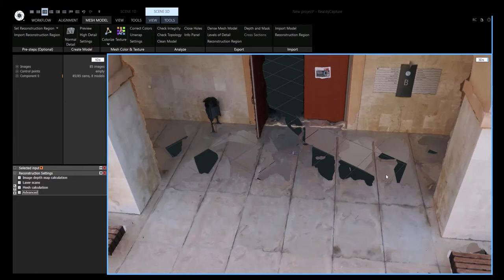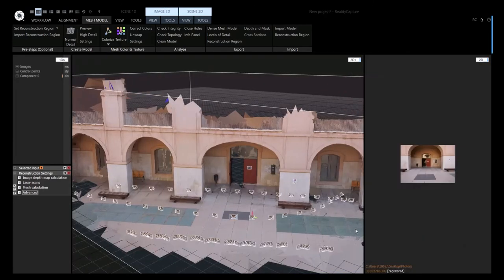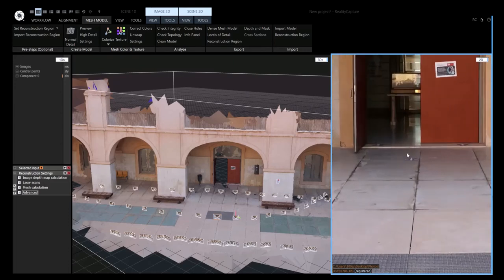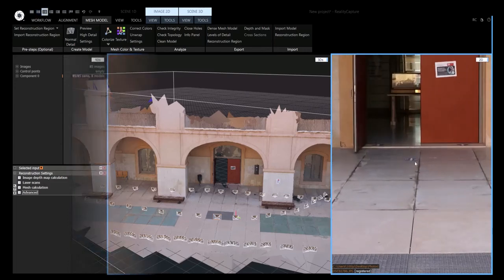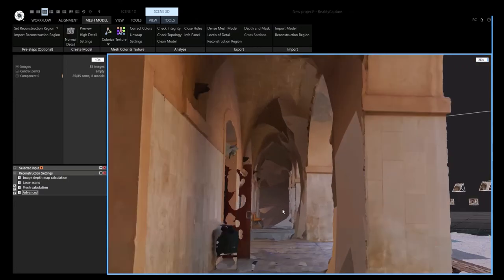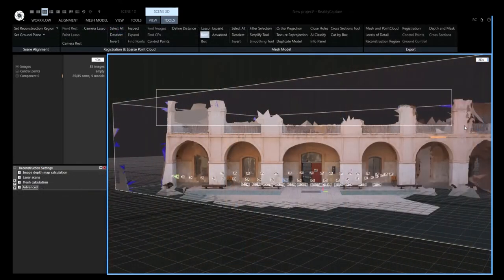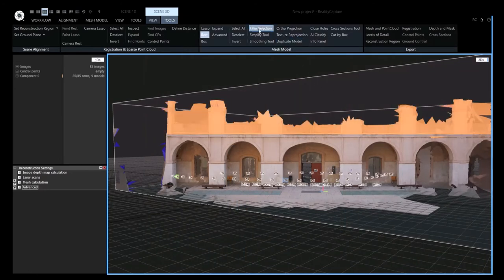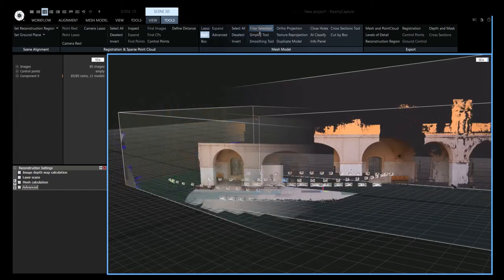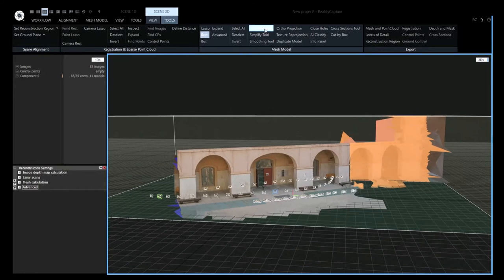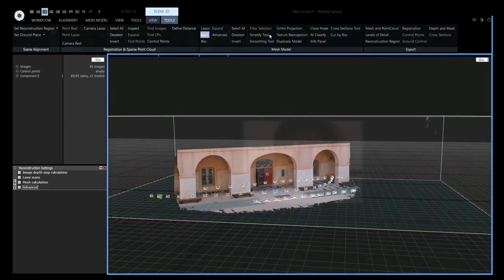In photogrammetry, what is not seen is not documented, which is why it is important to first analyze the area and then the photographs themselves when capturing the data. In the photogrammetric model, it is possible to find residual reconstructions generated by few points. As they have not been the target of capture, there are deformation and texture blurring, and this can't be removed. If the result is not as expected, you can return to the site to capture new data.